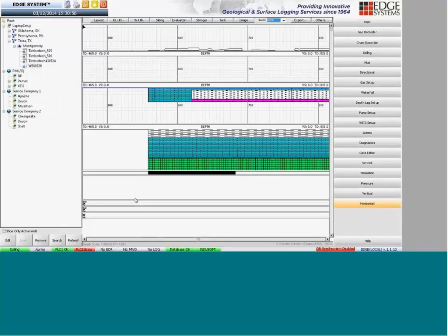And the nice thing from the software point of view, migrating the application is literally copying the application files to the new virtual server and installing InduSoft Web Studio and the SQL Server database in the new virtual server. So it's quite portable to port the application to a different system. There are a few settings, IP addresses, that we can customize. But obviously, we do not have to redesign the whole system to move the application to a different server.